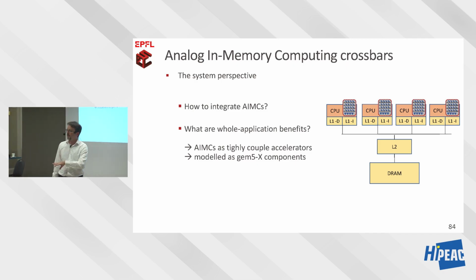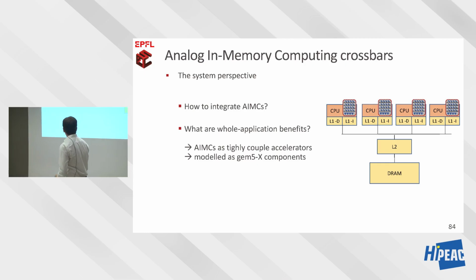And again, we interface them as custom functional units with the idea that each processor has a private crossbar, and these crossbars are programmed before a model is run, and then once initialized, they are never written to.